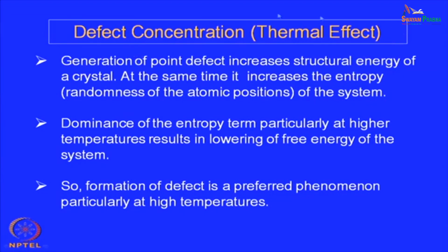Defect concentration, thermal effect. What we have discussed so far is that the defect concentration changes with the partial pressure, because it equilibrates with the environment, and depending on its preparation condition, depending on the environmental condition, the partial pressure, the defect concentration will change, and accordingly its conductivity, its mobility, its diffusion coefficient, all of them will change, whatever is related to the defect concentration, whether it is ionic defects or electronic defects.